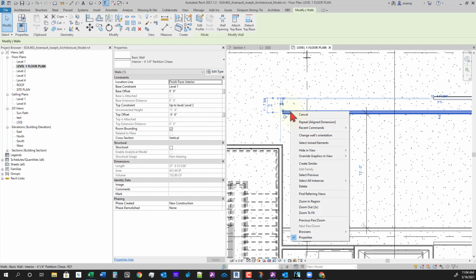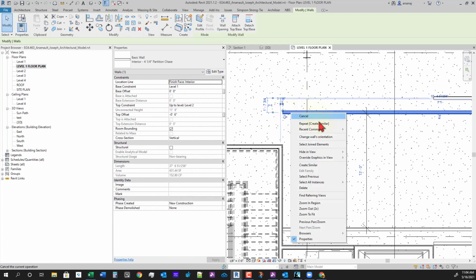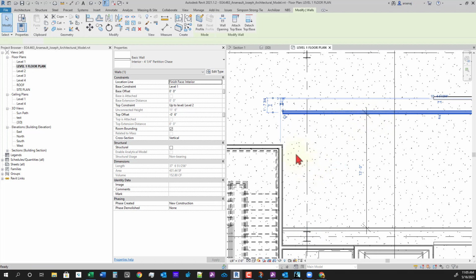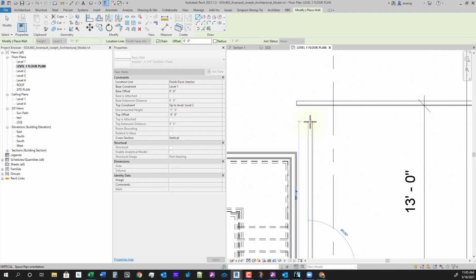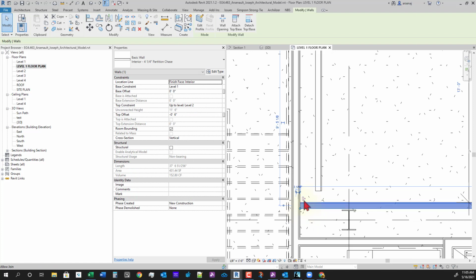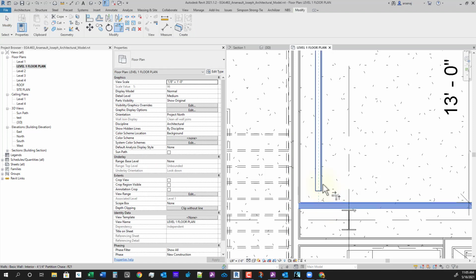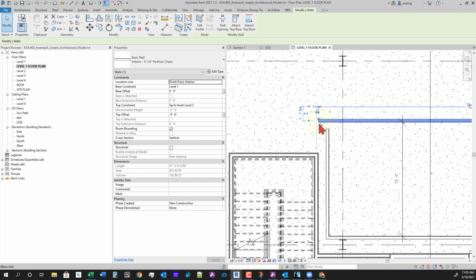All right, so I'm going to right click on this wall. I'm going to hit S. Actually, we'll automatically select create similar, or you can right click on this wall and create similar. And actually, I'm going to put this wall in front of our stair wall. I'm actually going to undo this by clicking the little T there, or right click on here to allow join, and I'm going to join these two walls together. And just do the same thing, use fillet or trim corner is what they're called here. I'm going to allow join for these two walls.